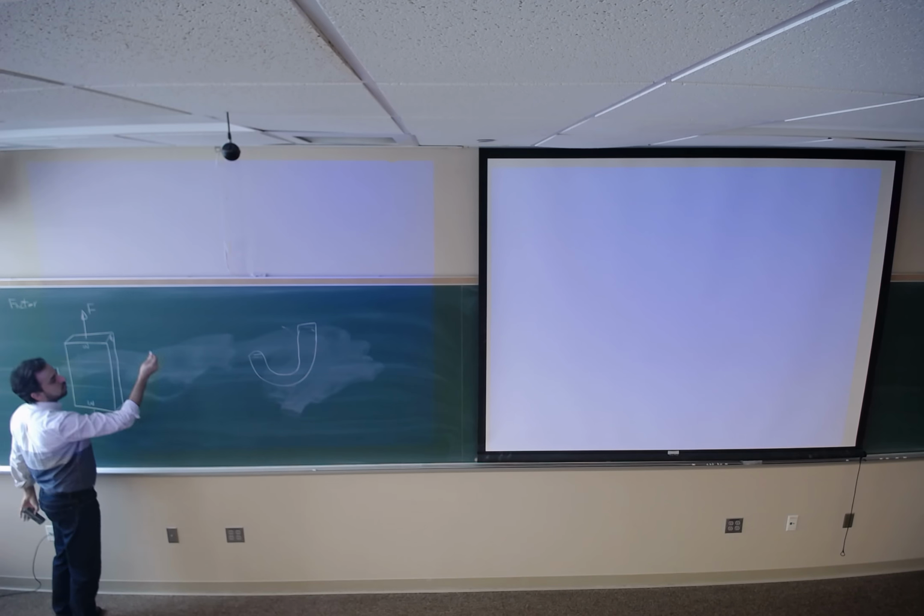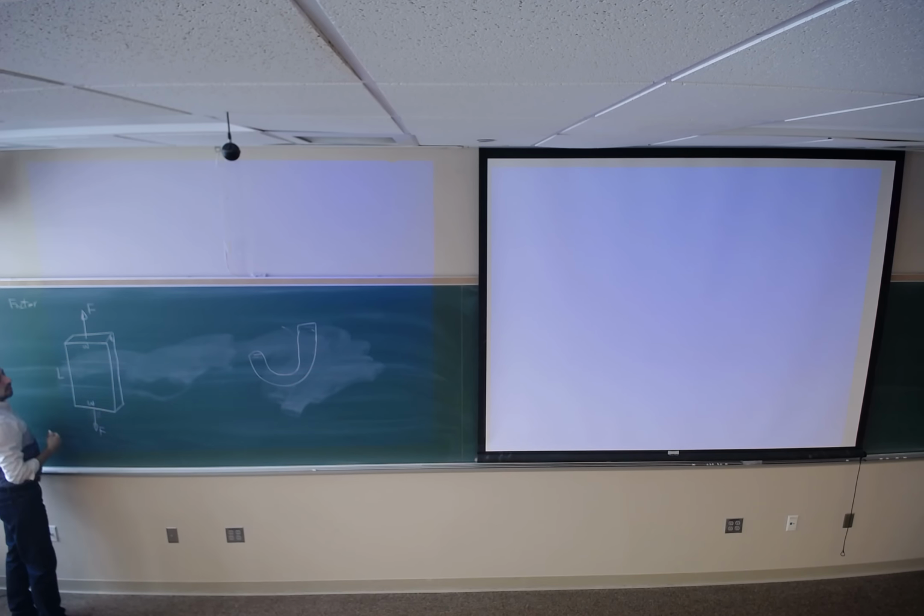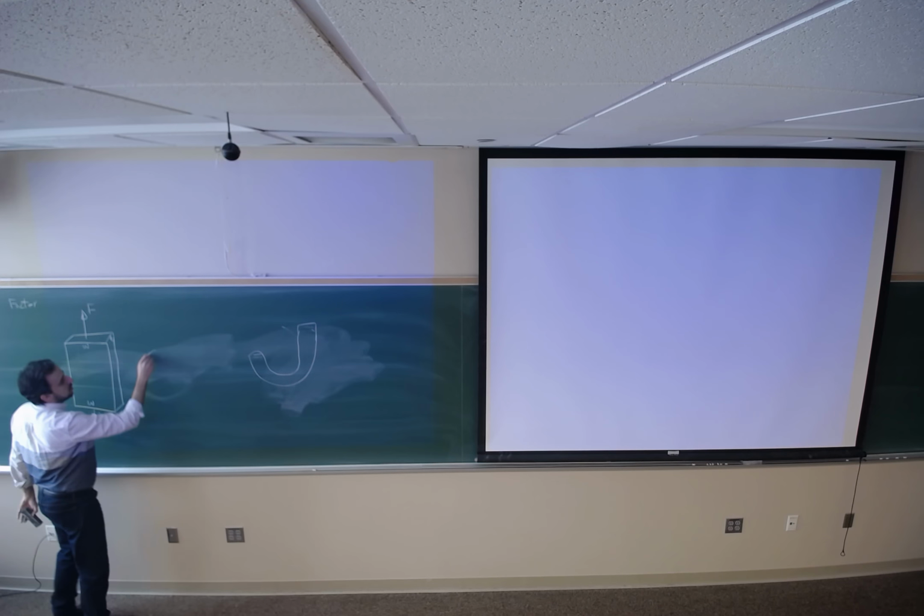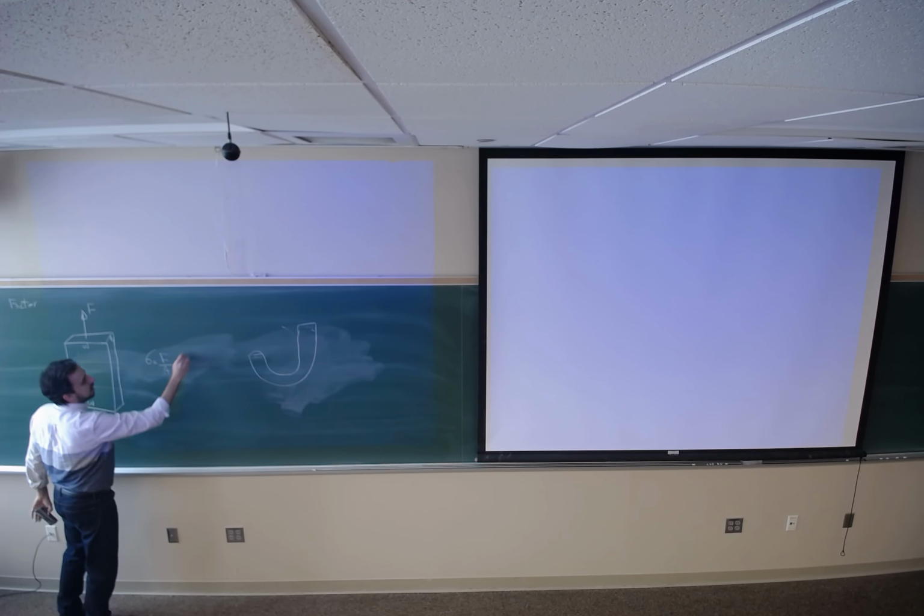If I ask you what would be the stress at any cross section, we can just cut this bar at that specific cross section and draw the free body diagram. Two forces apply to the cross section. One goes up, the other one at the other end goes down. So the sigma would be force divided by the area, which is W times T. The force is applied to this cross section. And now we don't have any discontinuity on this cross section.